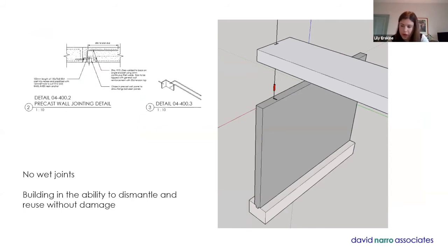Famously with precast, you have to have a huge front end because you can't reconfigure the elements once they're on site, they're there, you've got a shape. This method means that we can take them, we can change them. If there are late project client changes, for instance, or site discoveries, we've got units that we can use that are all relatively standard as far as we can. There are a few specials, but largely standardized units. We can change their shape, we can rebuild them in different ways. So the entire thing can be dismantled and reused in a completely different location if you wanted it to.